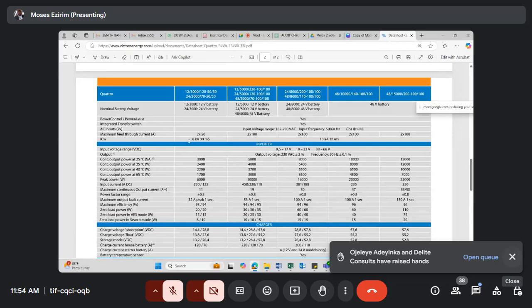Then you can't do it. If it's 6, then it is 24 volts that you do. If it is 48, you will need multiples of 4. Yes, I'll need multiples of 4. So you can't do it unless you tell the client that they should buy 2 more. Or you just make do with the 24 volt. Since it's residential, no problem, you can use the 24 volts. All right. In case of next time, just go for higher voltage. That's okay, sir.